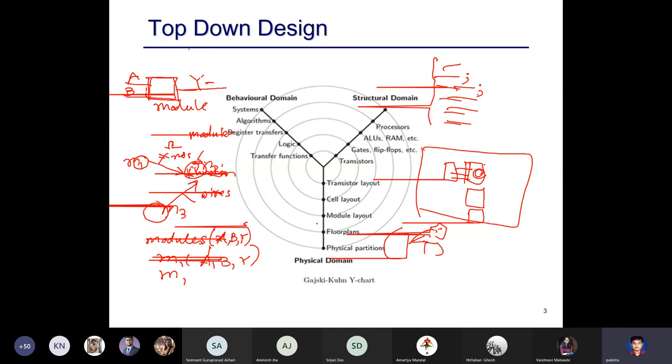In C, the program is sequential, one statement after the other. But since this is hardware, you can have a set of statements which are concurrent. So if you have a set of half adder modules and they are concurrent, that means they will add at the same time. There are 4 instances, and they add together. So you can have concurrent statements in a Verilog program, which you usually don't have in a C program unless you have special means of doing that. So this is the basic thing.